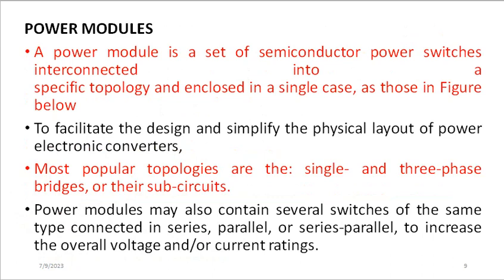So the next thing is power modules. This power module is nothing but a set of semiconductor power switches, the 6 we have seen, interconnected in a specific orientation, specific topology, and enclosed in a single case. If you want to use, let's say, 10 power diodes, instead of using them individually, they can cascade them, interconnect them, and put them in a single module, maybe with 2 or 3 terminals, just for you to use it. They simplify the problem for you.